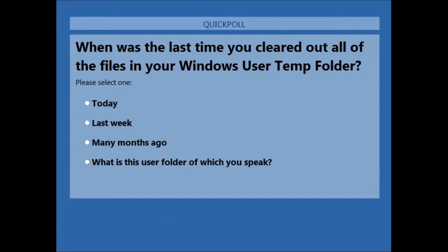Now, I'm not going to say you're going to get that type of performance increase immediately, but it certainly doesn't hurt, and in many cases, it's going to help you. If you find Civil 3D is crashing more than it should, get rid of all these things in that folder, and I think you'll be pleased.